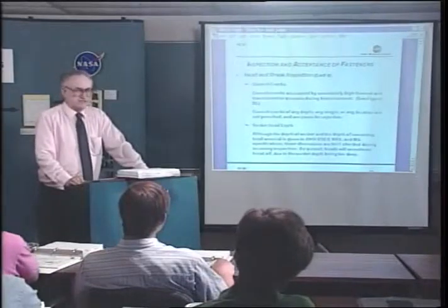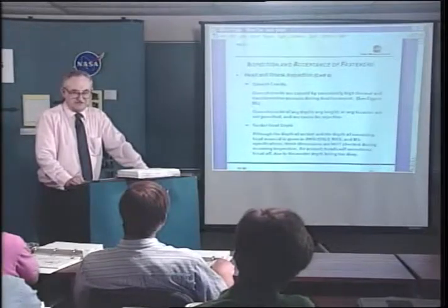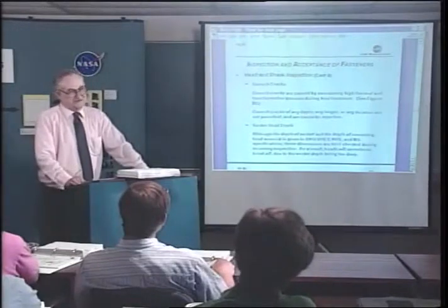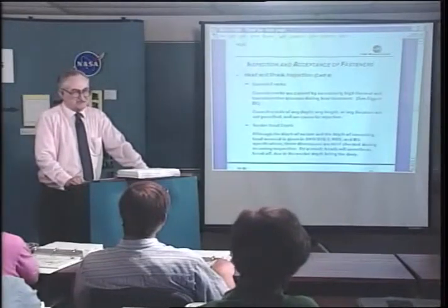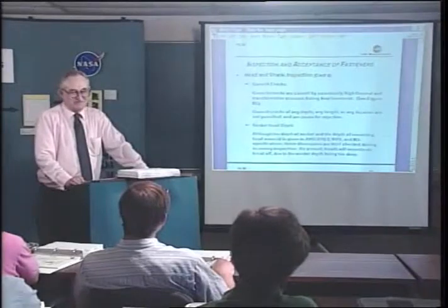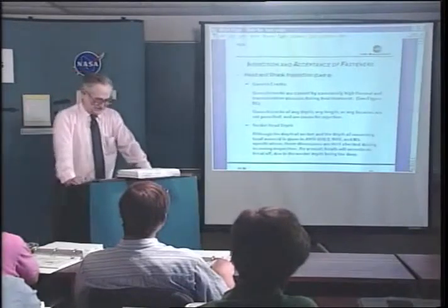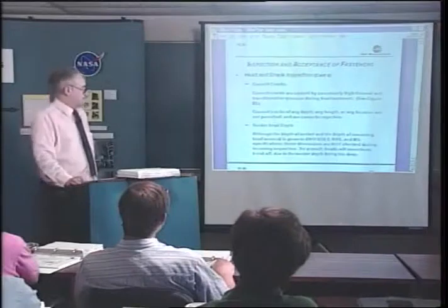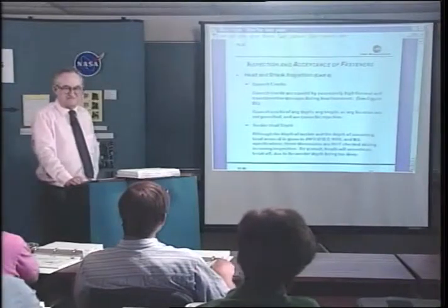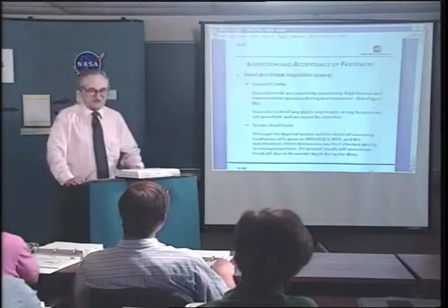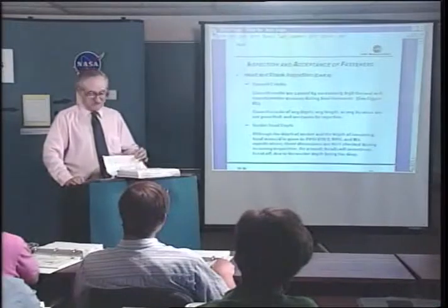Well, you see, in a socket head, if that depth gets too deep, you wind up with a small annulus of area is all you have left. If you get below the bottom of the head with the socket depth, you're in trouble, and that's what was happening. And although everybody talks about them, they're like UFOs, no evidence there.